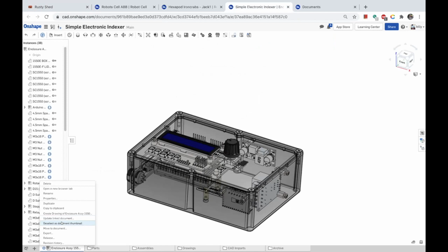I'm scanning through the document selector and it says robotic work cell, but all I see is a bolt. So one of the first things that you should do, and very few people are doing this, is that you need to select what you want to have show up. And then I don't care what you do, what the representation of the part that you're working on does, it shows up as this image right here. So you need to lock that down.